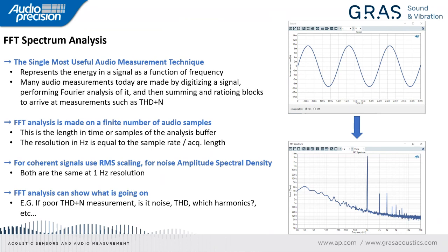It takes a time domain signal, such as a sine wave, and represents the energy in that signal as a function of frequency. And this can be incredibly useful because out of this representation can come all the measurements we want to look at.